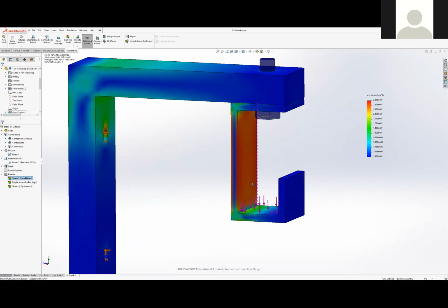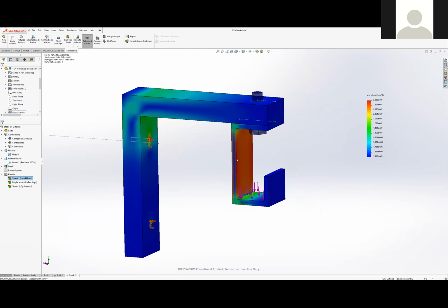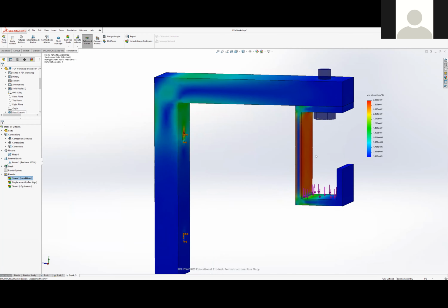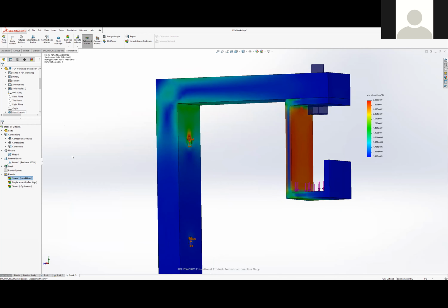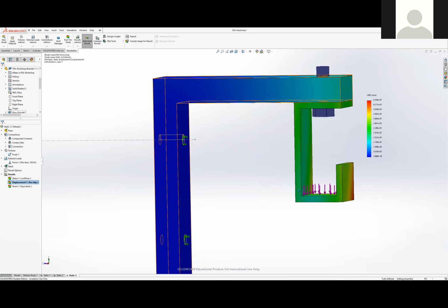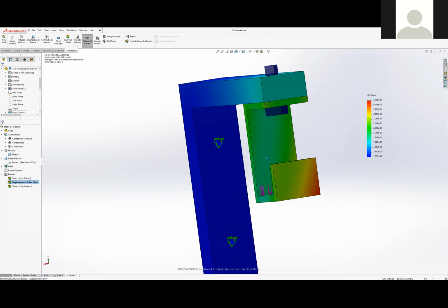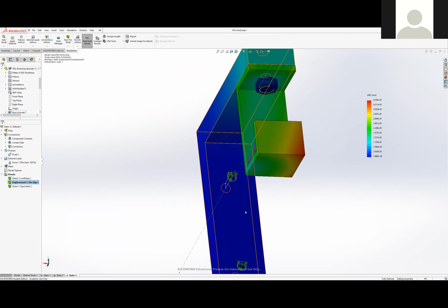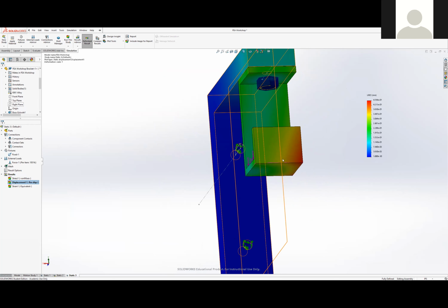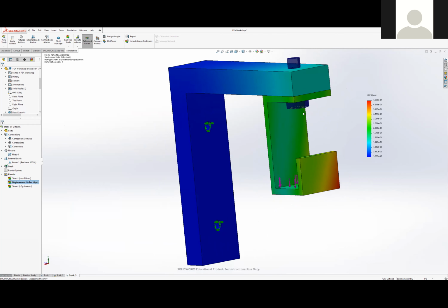Okay, so you can see we ran the FEA and it's on an assembly level. You can see that most of the stress is put onto this face of that rack, as expected, but it's good to have a sanity check that this is indeed where the maximum stress is. You can also see the displacement. The bottom of the hook will displace the most. Even though this is symmetric about the right plane, there's more displacement on the right side of the hook. This is due to that preload I was mentioning earlier.